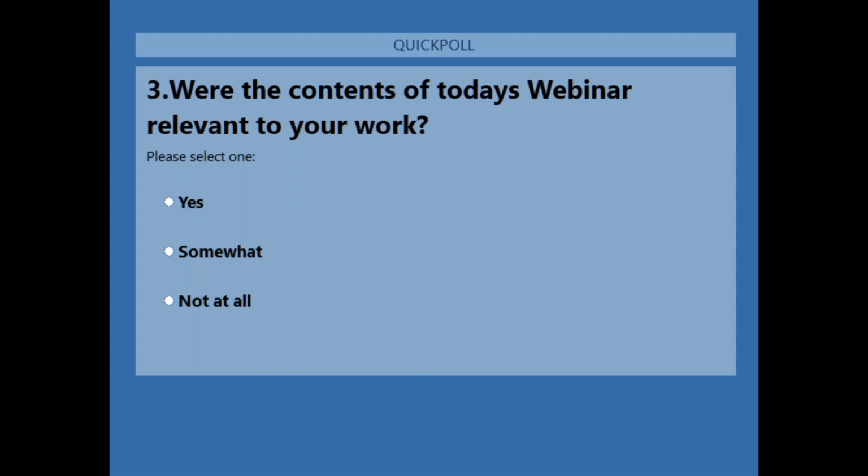See, BIM 360 cannot be used offline. When I say cannot be used offline, that means once your project is being collaborated on the cloud, you could open that information in your native application, but the information of that particular project will not be stored on your local machine. It will be stored on the cloud. So definitely an internet connection is required when you work on the cloud between Plant 3D and BIM 360.